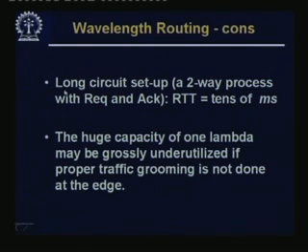The disadvantages or the cons are the following: long circuit setup time. This circuit setup time will be in the order of tens of milliseconds. The way these circuits are set up is that the source sends some request, and the request goes down. All the nodes on the way first have to set up their own local switches in that particular fashion, and then they will acknowledge and say that okay, the light path has been set up. So, all this communication takes of the order of tens of milliseconds.